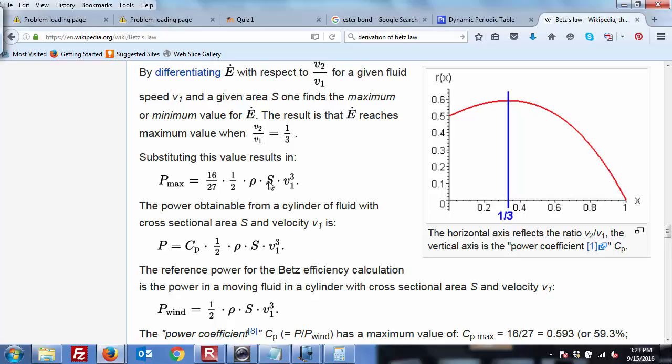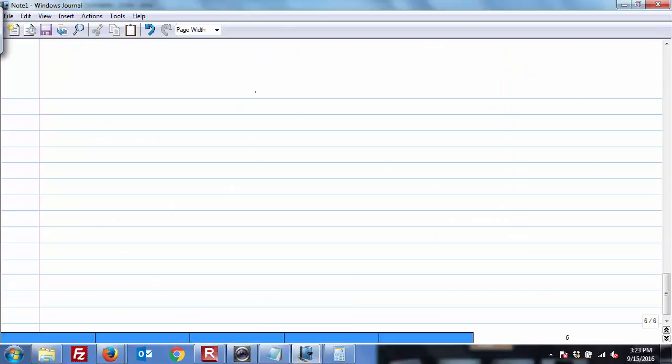So really all we did was take volume and turn it into area, and take one of those lengths, stick it over there, turn it into velocity, stick another time in the basement, and now we've got velocity cubed. So let's just take that. Power equals efficiency times 1/2 density area V cubed.